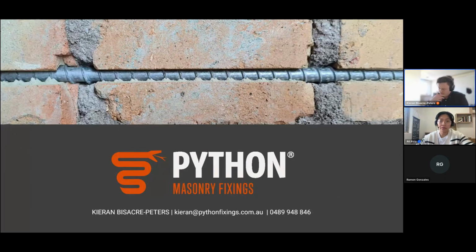Yeah, so out of plane displacement, sometimes you can prop them back into place and then introduce another structural system to brace the wall, like steel posts or timber strongbacks. Otherwise, it depends on how bad it is, the extent of the damage. But sometimes it'll just be a rebuilding situation.